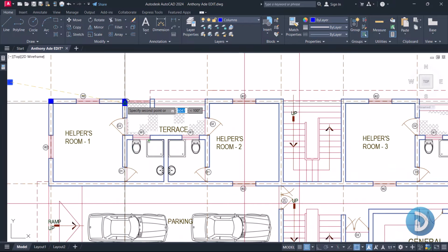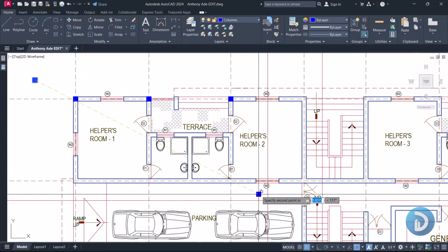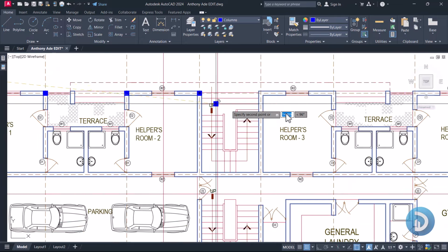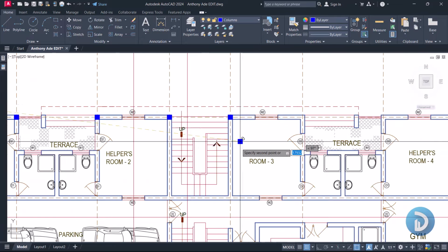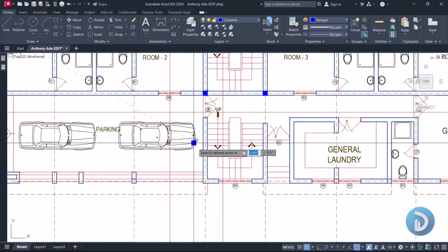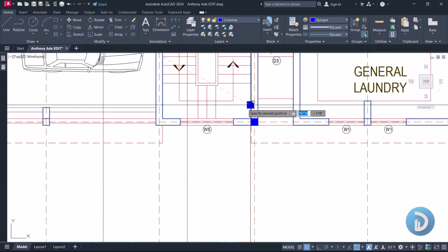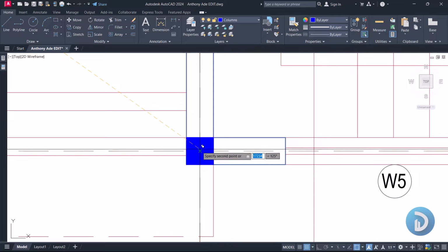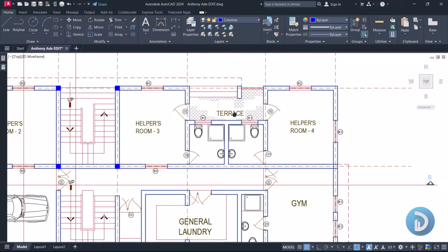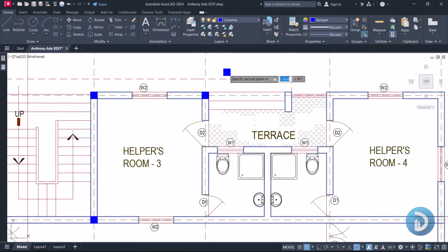So we can also run another column in between these walls. So we'll pick this next position, and at the boundaries of our staircase, we will have columns there. Then also at the boundary of this other staircase, we'll have another set of columns here. Okay, then we'll move to the right hand side. This should be the next proposed column position.